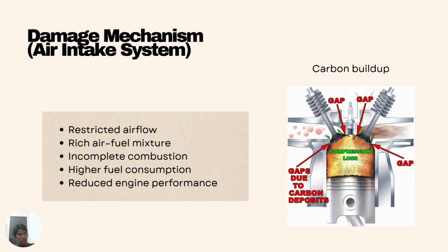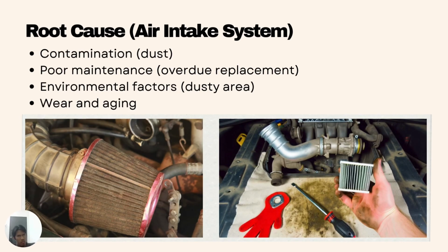Next is damage mechanism. This is why we don't want the air system to be damaged, because it will restrict the airflow. Too much air fuel mixture means incomplete combustion, so there will be carbon deposit at the gap, and it makes compression loss, higher fuel consumption, and reduced engine performance.